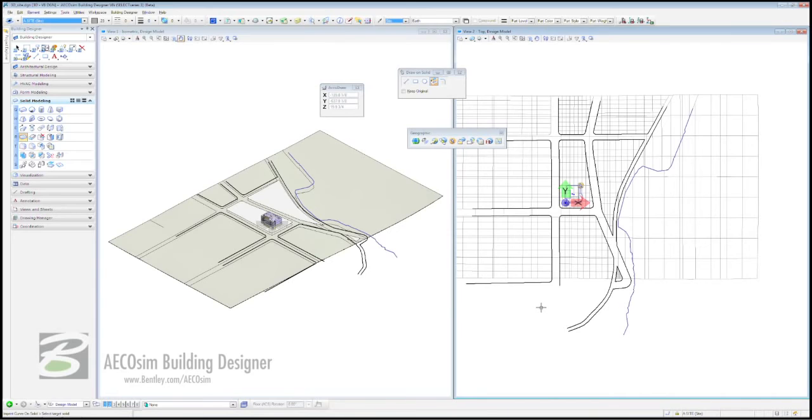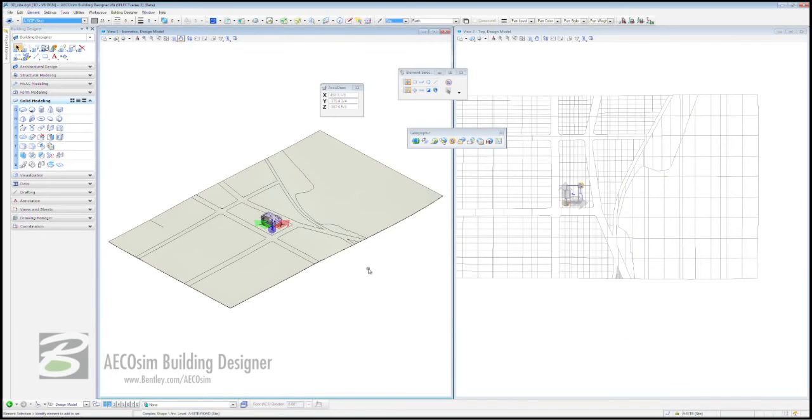And you'll notice how your site has almost changed perceptibly in the right hand view, because the terrain has now changed with it. What we can do now is simply delete the lines that we copied to create that stencil on top of our site. Now, with those lines imprinted onto the surface of our terrain, what better thing to do than actually make them a little bit more real, in the sense of giving them some more depth.